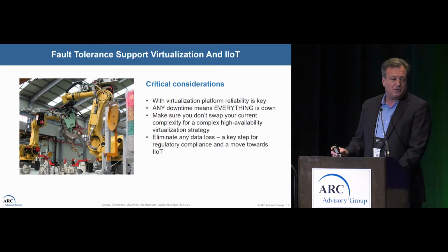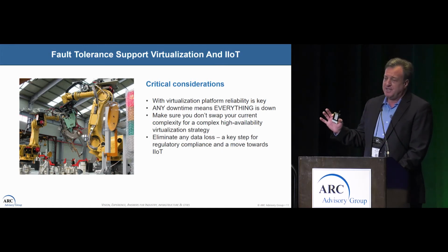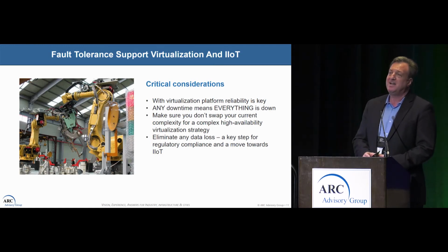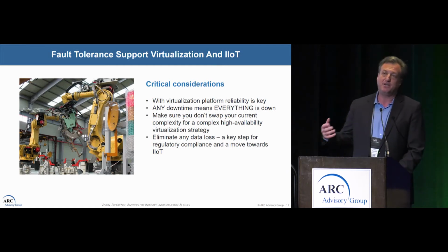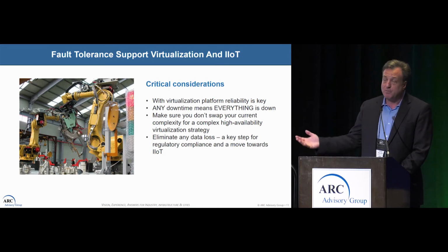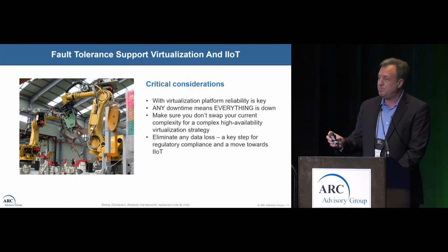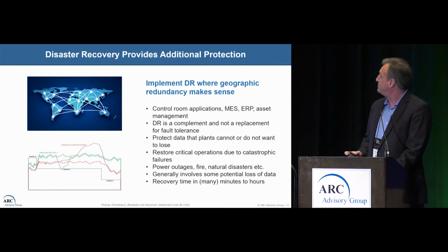Another consideration, as you're going through virtualization, especially in an IIoT world, is that the loss of any connection is a problem. At one time you were worried about the flow levels, temperatures, and pressures on and off connections that might go to a PLC, DCS, or a PAC. But as these low-cost sensors are being installed in assets and sending information up to the cloud, say for asset performance management, the criticality of those measurements and the ability to keep them up is now as important as your traditional control system measurements.